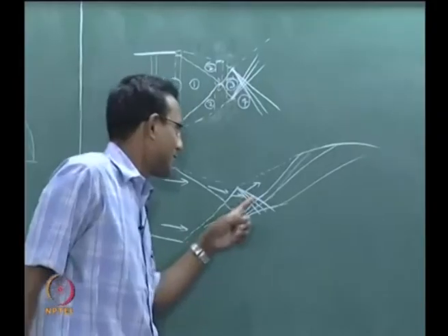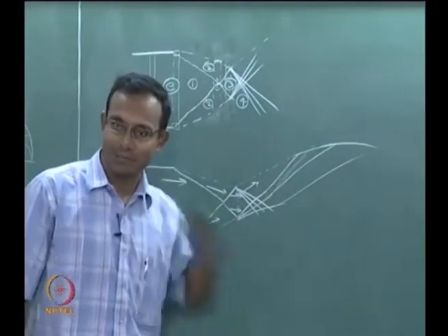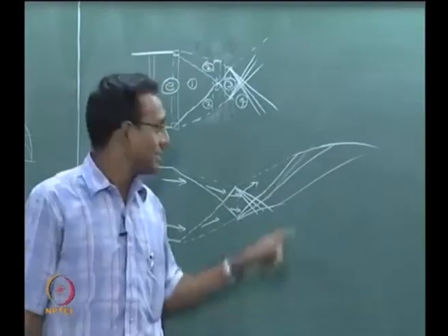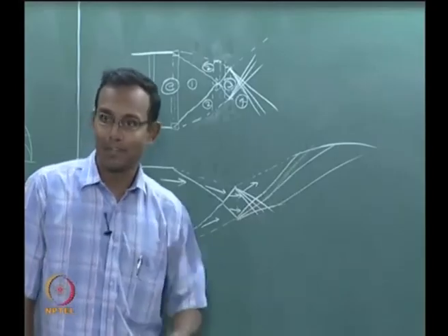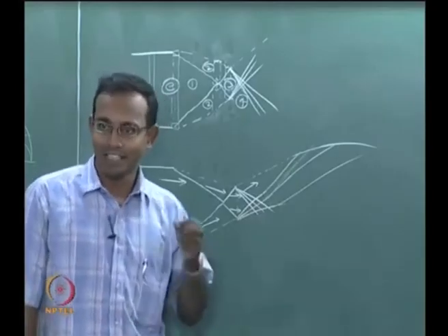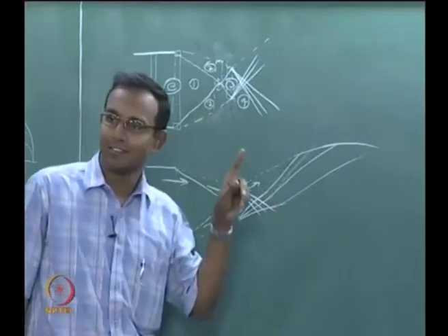What happens when an expansion wave goes and hits a boundary which is again adamant? It is going to say the pressure has to be fixed. Expansion tells I have to decrease pressure, so it will be replaced by a compression wave which will tell increase pressure. Why is it a compression wave versus previously it was a shock?